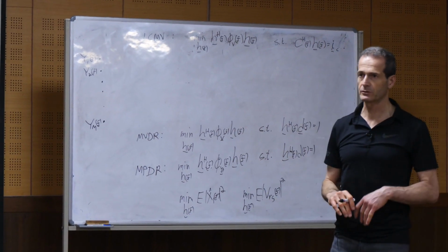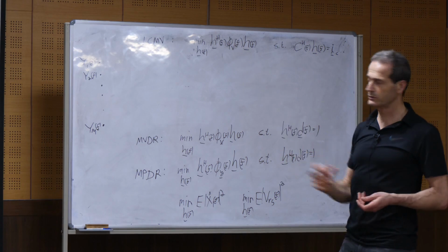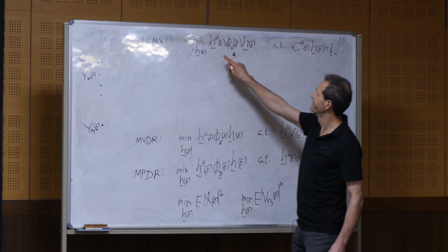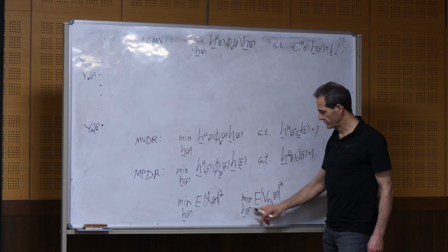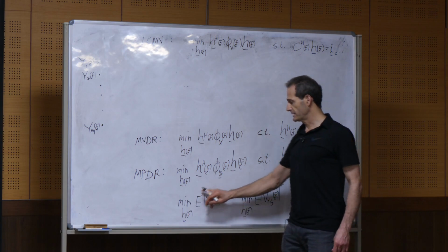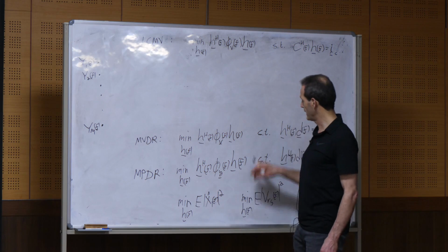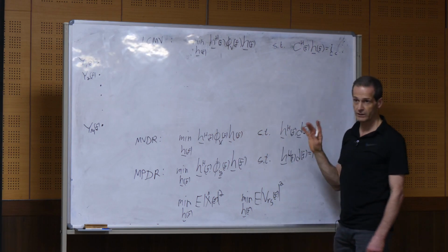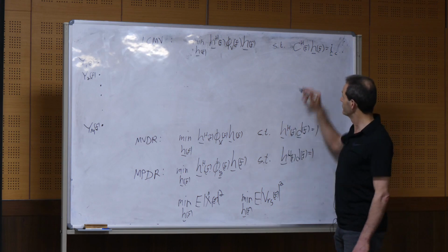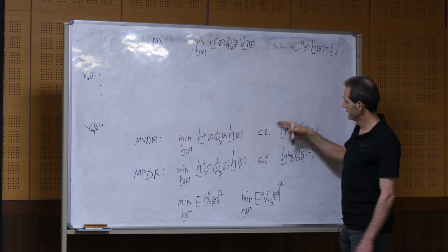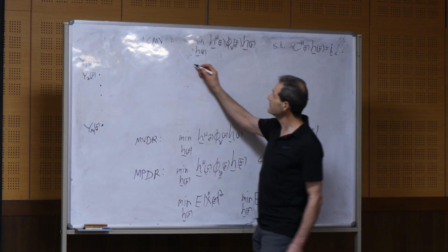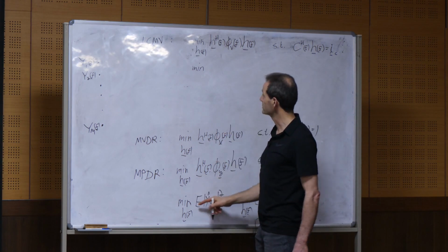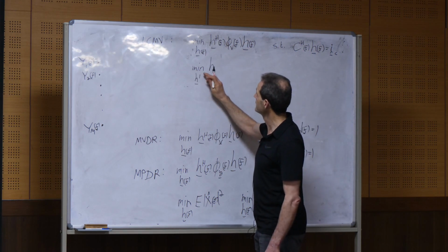But I don't want to talk about the solution. It's not difficult to find, and we already showed what the solution is, but I want you to see the equivalence. Instead of minimizing the variance of the residual noise, we can minimize the variance of the estimate. It's the same under these conditions, as long as one of the constraints is the distortionless response constraint. So we can minimize the variance of the output of the filter. We can write it like this.